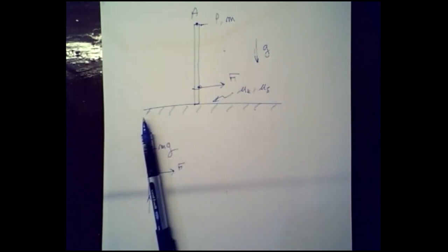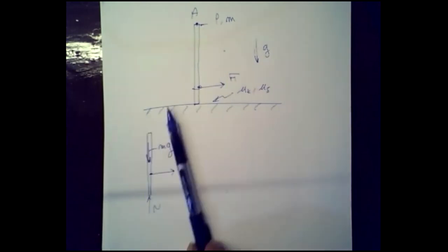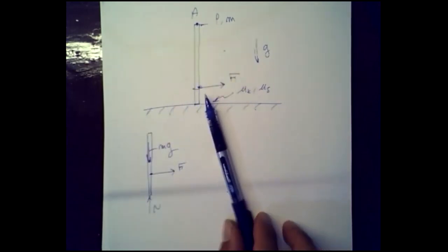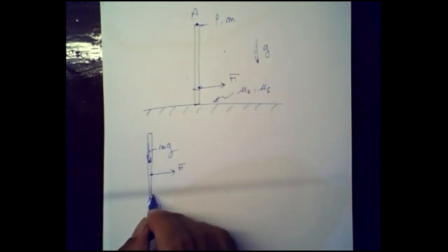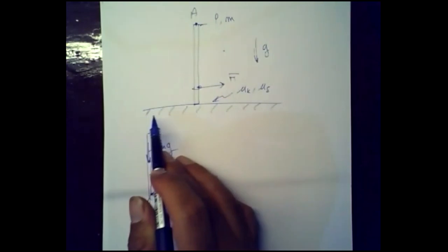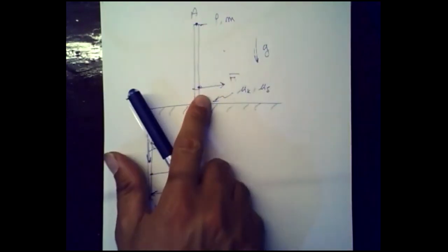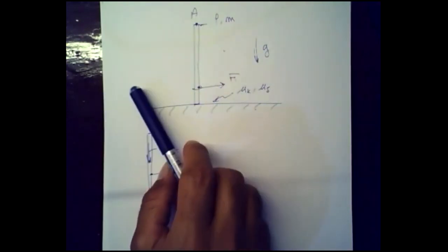If I ask you what is the maximum force or what is the acceleration of this, when this guy is on the verge of slipping, then you want to put the friction equal to mu s times N. Otherwise, you don't know what the friction is, and then you can solve for it. But what you should know is that the friction will always oppose the movement of that. So if this guy was frictionless, as a result of this force, what do you think will happen?